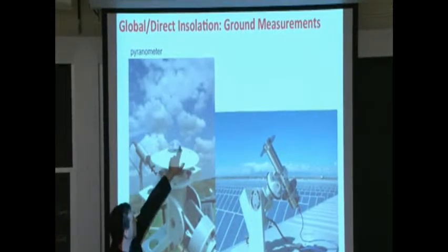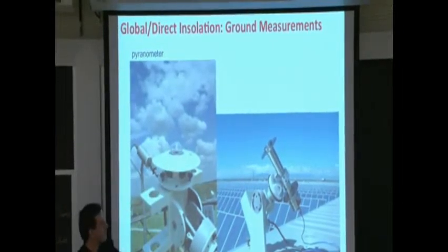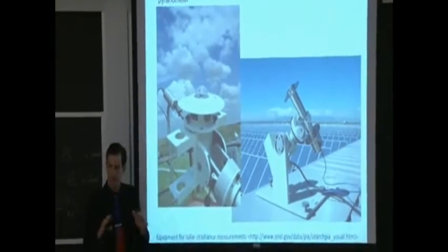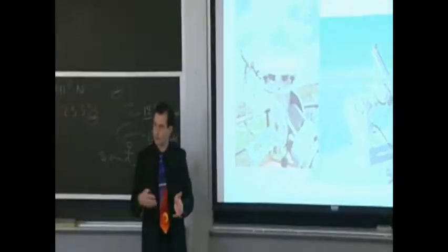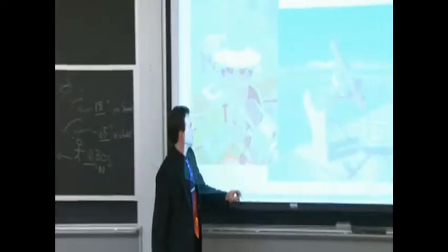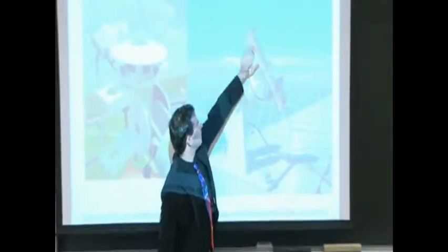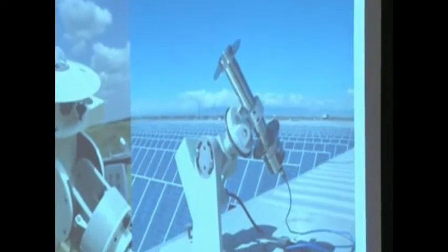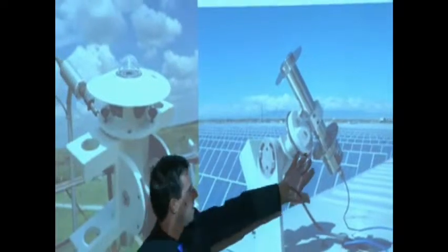This is a full hemisphere, measuring the sunlight coming in from all angles. There's a small little sensor right here. It's lying flat, and that glass is essentially allowing the light from different angles to get in to the sensor. And this is a very narrow, solid angle of the sky. It's probably just looking at the sun, or in a particular direction rather, plus or minus 2.5 degrees in either direction. So it's a very limited solid angle of the sky.